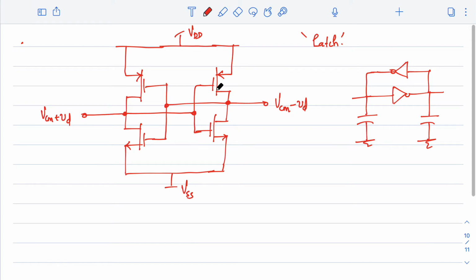Rather, this will work based on a clock, right? Because we have a sample and hold circuit where it works on a clock. So when the clock is high, we have a voltage coming in, and at the sampling instant we have the voltage which is stored across the capacitor, or that is the voltage what we have, right? So we will not directly connect this to these two nodes.